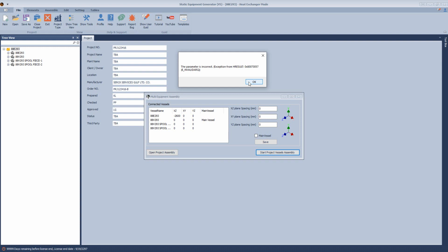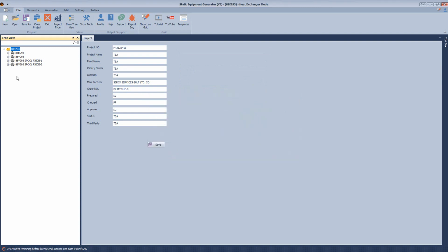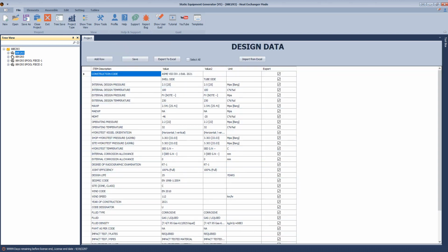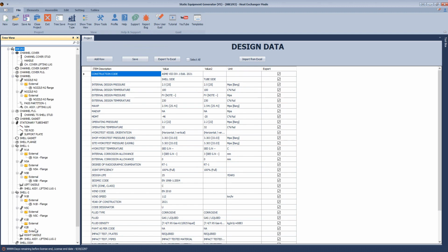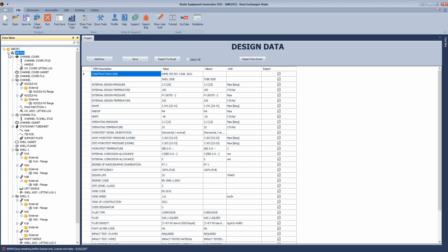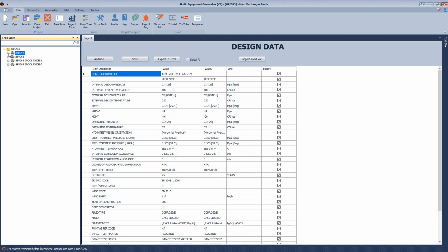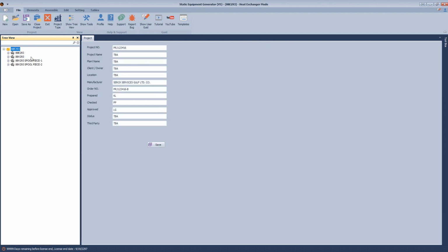So how to solve this issue? Okay, the solution depends on renaming one of those assemblies, the project name or this equipment. If you already created this assembly for this pressure vessel, it is not the correct or suitable way to rename it, because at that time you will need to rename all parts again. So the right solution for this issue is saving this project as another project with another name.